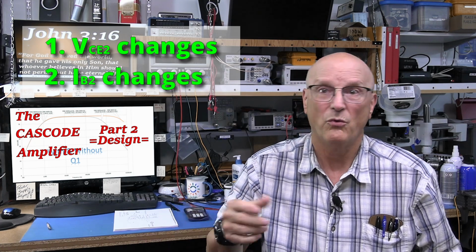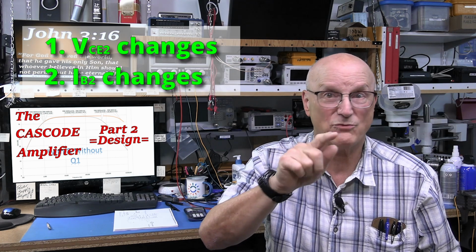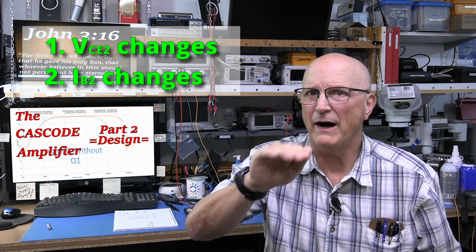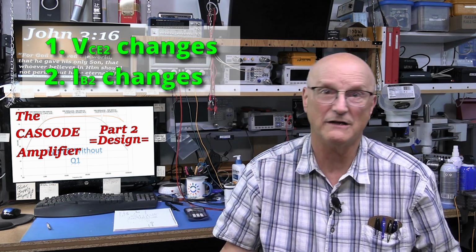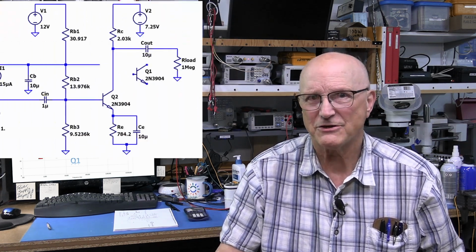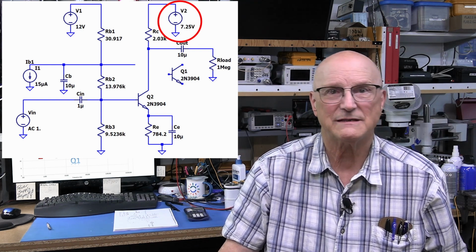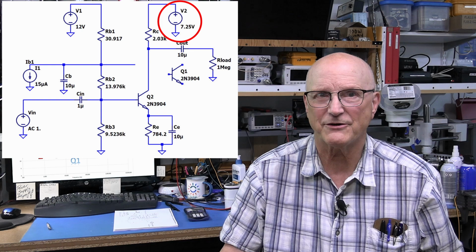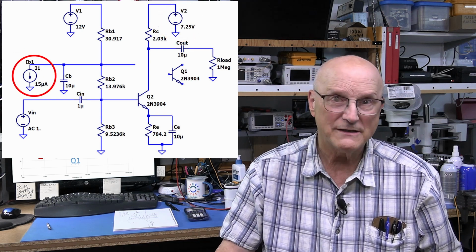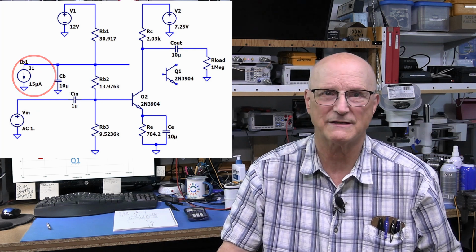We have to add a current source to that point where the base was connected so that the bias current for Q2 would also remain the same. So, now the circuit looks like this in LTSpice. Here is the separate power supply for the collector. And here is the current source to simulate the existence of Q1's base.